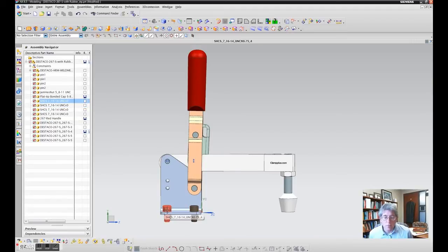On this level, you would also have the external forces through the fasteners holding it down to the table. And then obviously internally, there would be several internal reaction forces between the pins and the various elements. Okay, so that would be one load case, right? The second load case one might consider is what happens when somebody puts force actually onto the handle. So that's a separate issue.